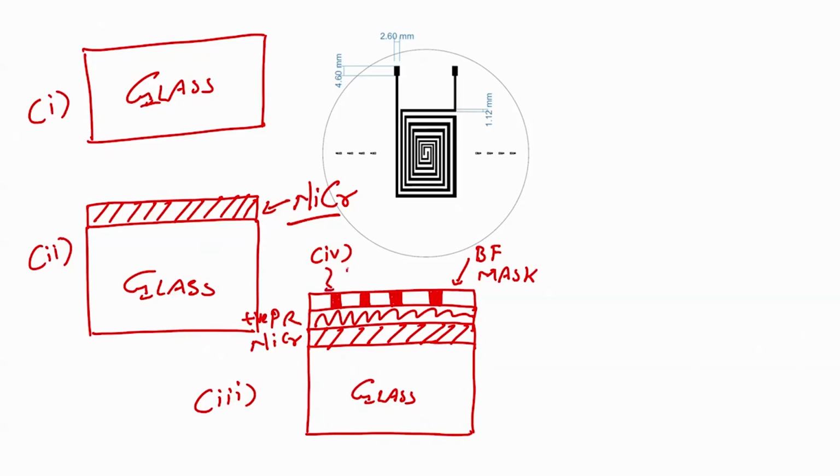So, if I expose this whole glass wafer, along with the mask and positive photoresist, with UV, what will happen? The area which is not exposed, which one? This one which is bold, like this. The areas which are not exposed will be stronger and the areas which are exposed would be weaker. So, the fourth step would be to load the mask and perform UV exposure.